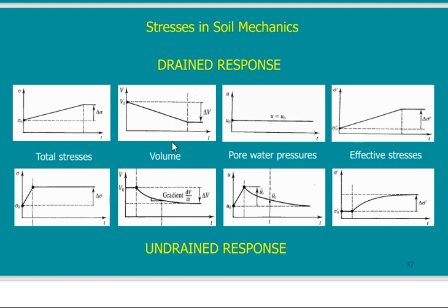What happens with the volume? I said the volume is the opposite. Here it is the opposite of this chart. When I increase the stress, the volume decreases. Here, when I increase the stress, the volume does not change at the beginning because I told you the water is trapped. So it has to have some time to be pushed.